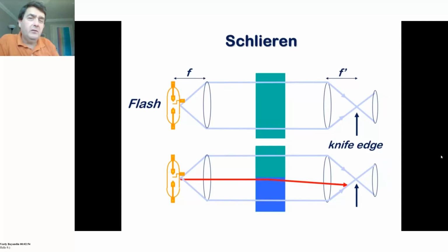So we're cutting off basically the bottom half of the light that's being focused. What this means is when we have the wave moving through the material, the light that is being refracted, in this case refracted down, does not get to the camera. So you don't get that extra brightness, you get the areas that remain a little bit dark. This enables you to see what is happening in a little bit more detail.